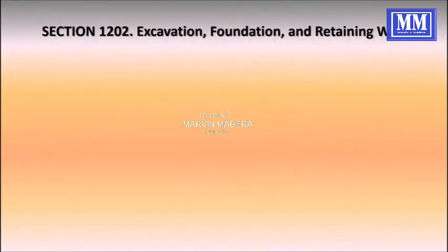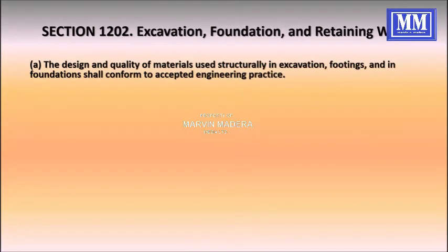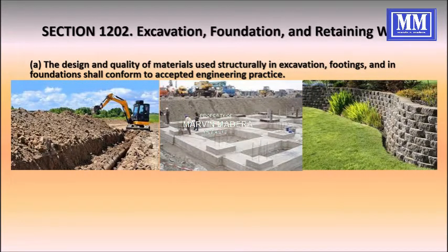For Section 1202, the Excavation, Foundation, and Retaining Wall, the design and quality of materials used structurally in excavation, footing, and foundation shall conform to accepted engineering practices. So in this section, we have the standards for all the materials in the excavation, which are standard in the Department of Public Works and Highways. In the excavation, all fill materials should be approved by the engineer in charge.